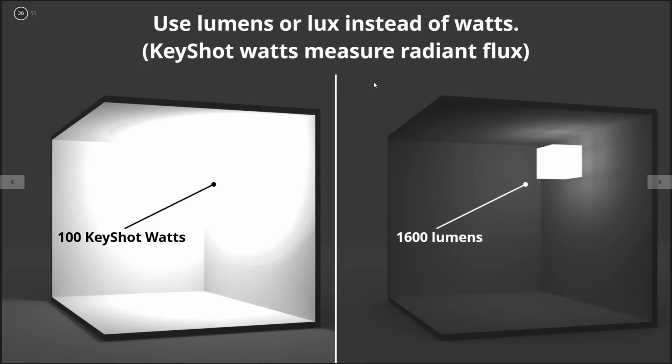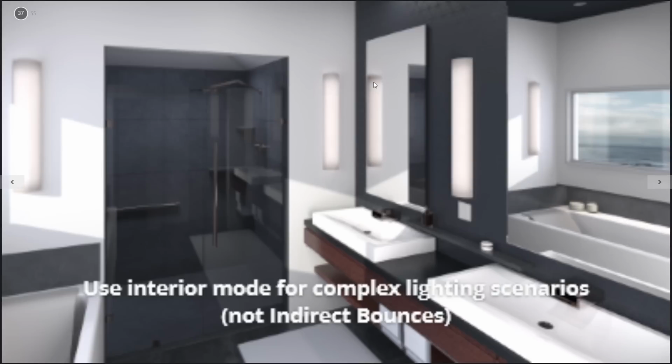First, use lumens or lux instead of watts. I know we're probably getting questioned, well, then why the heck are you keeping watts in there? That's a very good question, and we're going to have to address actually including those watts in there or not in future releases. But yeah, a lot of times it's going to come down to the watts. The intensity that you use with watts is just too much. Those little white hotspots are going to be less visible if you use lumens.